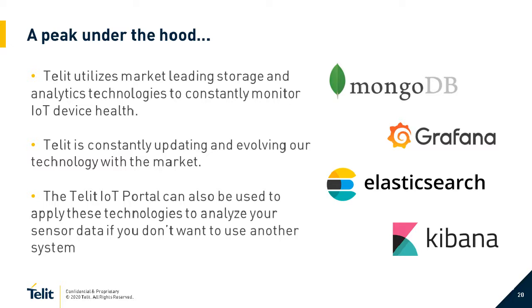The big hop is that if you're using narrowband or Cat-M LTE solutions, the latency of the link can be fairly slow. So you do have to design your applications and know what type of cellular module you wish to use based on your desired use case. This is also why we still see a number of IoT use cases using Category 1 LTE today, because it does have a better performance envelope.